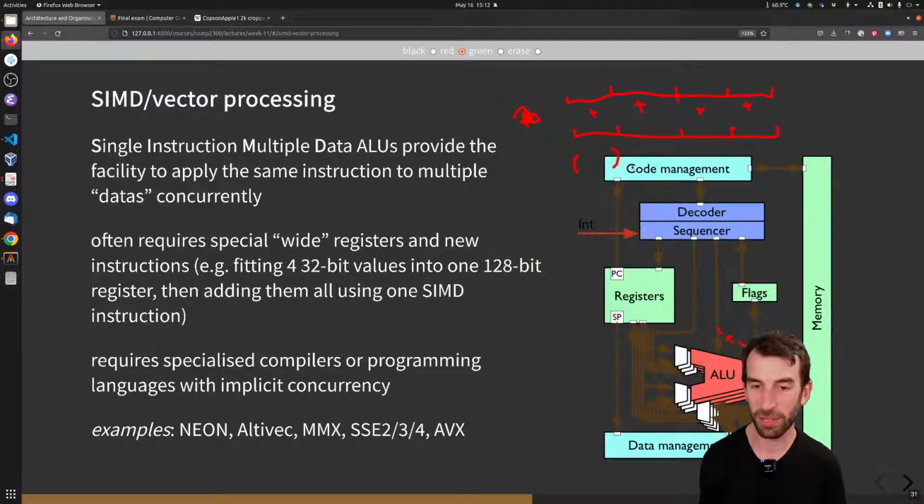And your micro:bit can actually do this. It has some SIMD instructions. It's only a 32-bit processor, so it can't do very much, but it can do a bunch of arithmetic with 4-bit fields in a 32-bit register, 4 8-bit fields, or 2 16-bit fields. And it can do some crazy things like add and multiply things together.